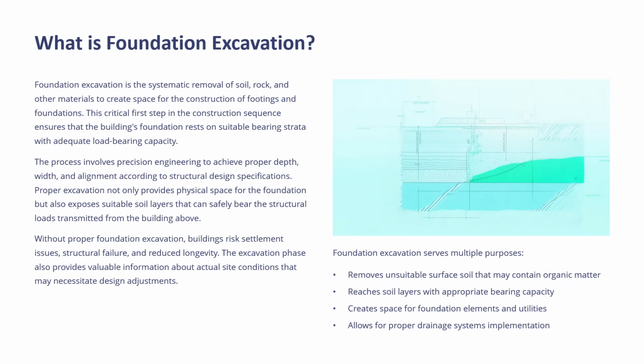So it is the systematic removal of soil, rock, and other materials to create space for construction of footings and foundations. This critical step in the construction sequence ensures that the building's foundation rests on suitable bearing strata with adequate load bearing capacity. The process involves precision engineering to achieve proper depth, width, and alignment according to structural specification.